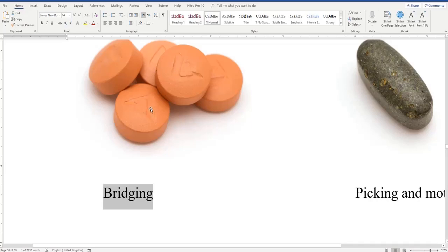So what it's doing is disfiguring, or let's say covering, the logo rather than getting inside and outside to leave a sharp logo. We call it bridging, okay, because it's not getting inside deeply and then outside. It makes a bridge. And one reason is also the viscosity. You see why viscosity is very important?